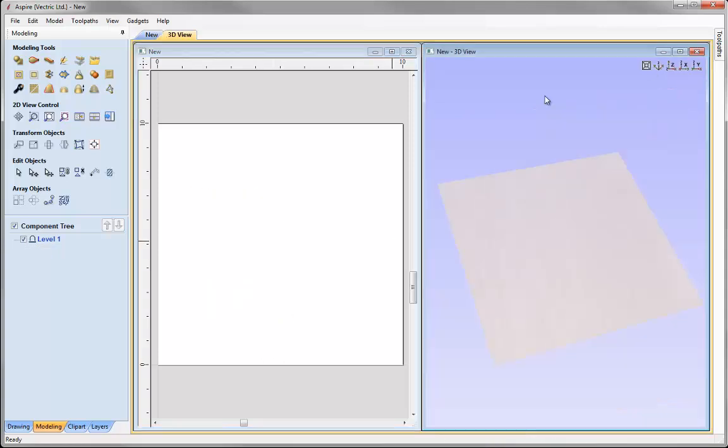Put that back in isometric view. So I've seen a number of ways that we can import data into the software to create a 3D component. We also have ways to export 3D data in different file formats. Typically in Aspire the end result is to take your model and the vectors, calculate your toolpaths and then run those toolpaths on your CNC machine.